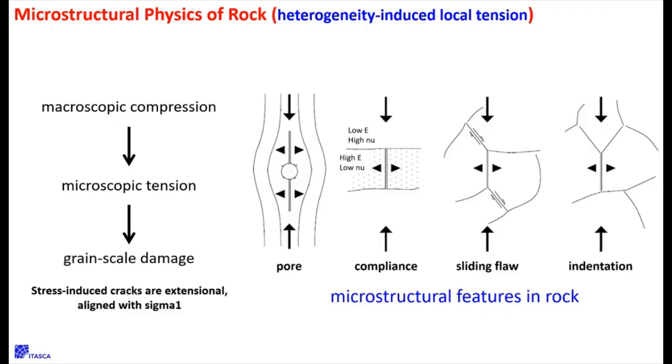I spent about three summers ago looking at every paper I could find in the published literature to try to find little pictures of two tiny grains breaking in shear. And they're almost non-existent. The shear response is a macro response, where an entire specimen begins to fail in shear. But at the local level, you squeeze rock, and because of these mechanisms, this heterogeneity, you get tension, and it's the tension that makes it start to break, okay?